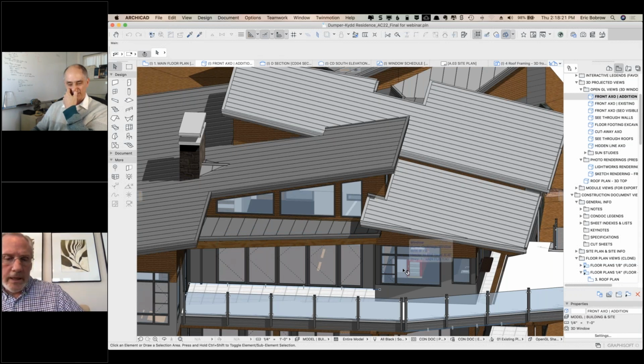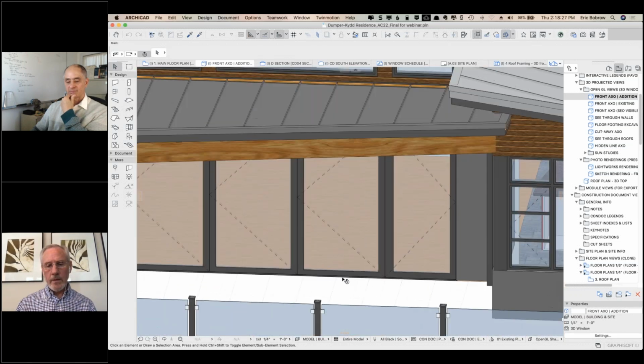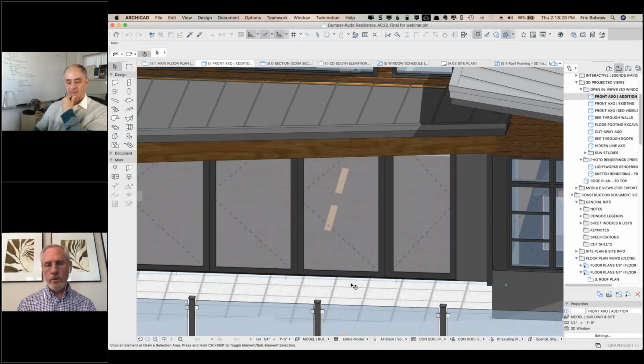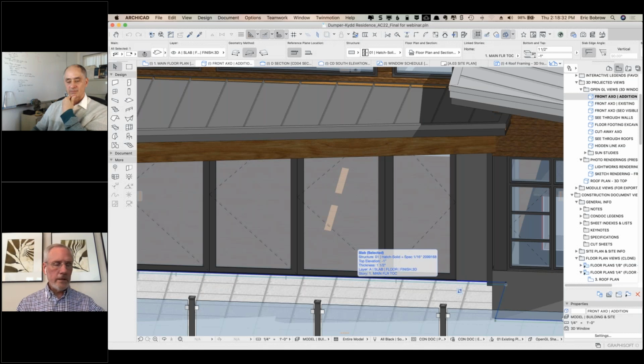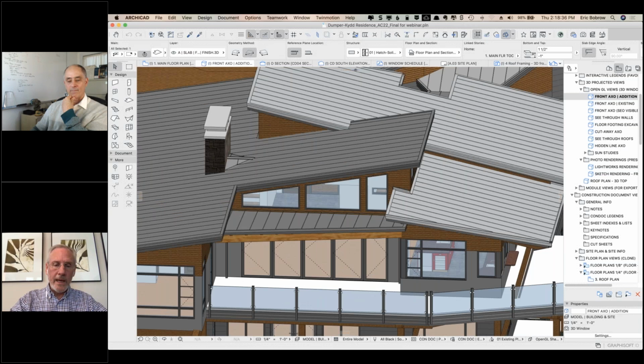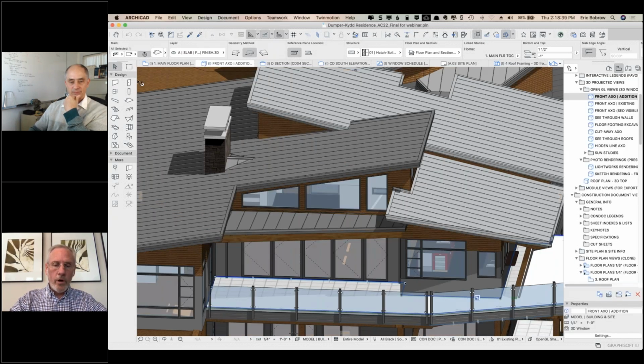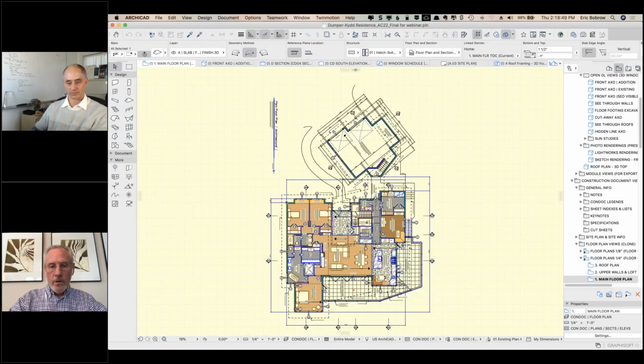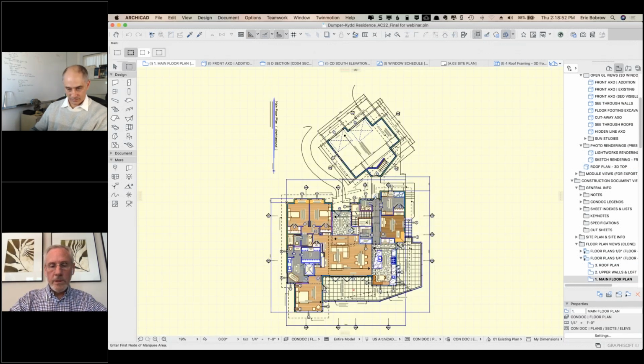Well, the deck, the client really wanted a walkout flush deck. And in British Columbia, where I live, the code here in Canada is that we have to have a minimum of 6 inches drop at the door down to any patio deck like that to prevent water, obviously, from building up and coming into the house. So one method of achieving this flush deck is that it was constructed with a floor framing system that would be typical of any deck, except it's set down from the floor level by 6 inches or so nominally,